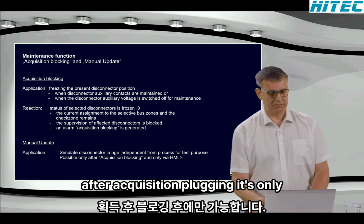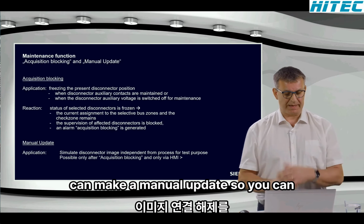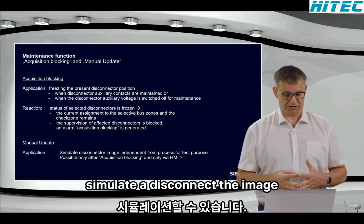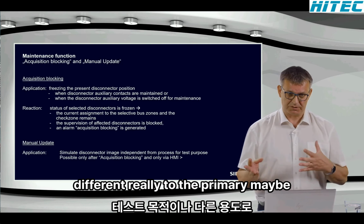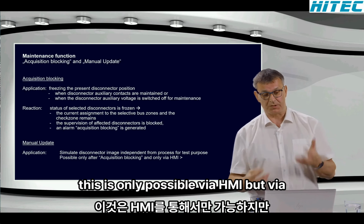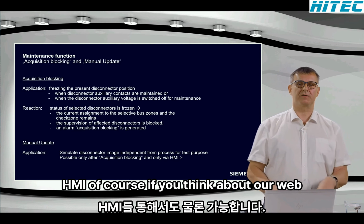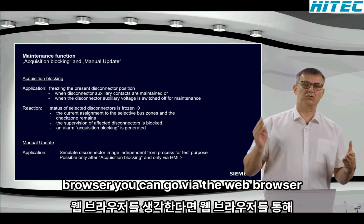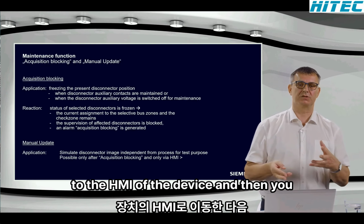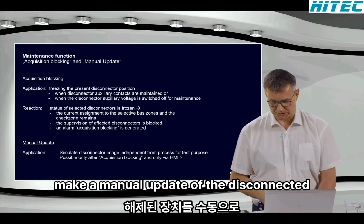After acquisition blocking, it's only possible after acquisition blocking, you can make a manual update, so you can simulate a disconnector image different really to the primary, maybe for testing purposes or anything else. This is only possible via HMI, but via HMI, of course, if you think about our web browser, you can go via the web browser to the HMI of the device, and then you can also make a manual update of the disconnector positions via the web browser.